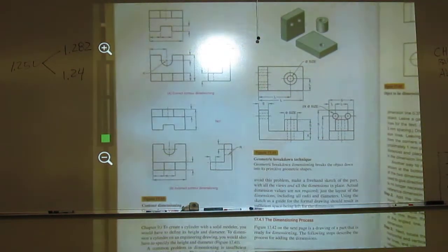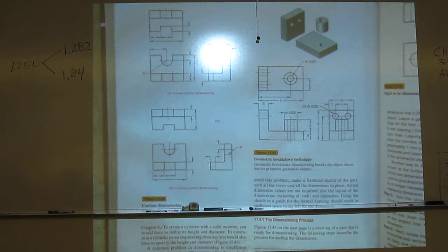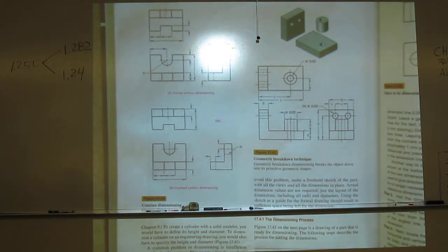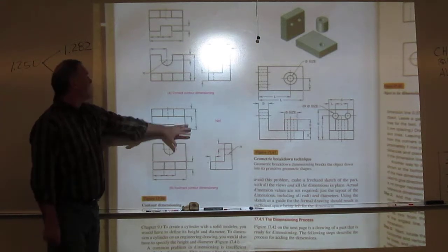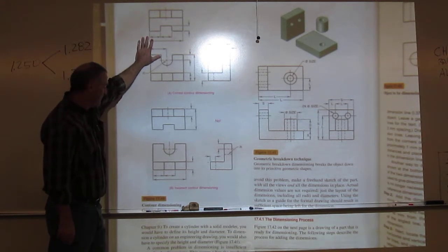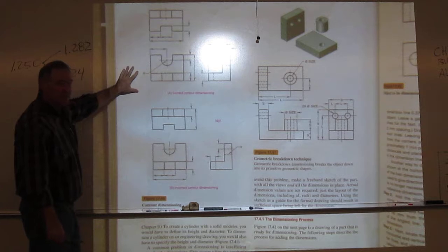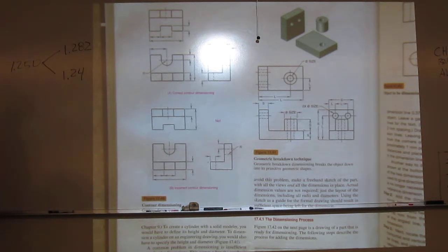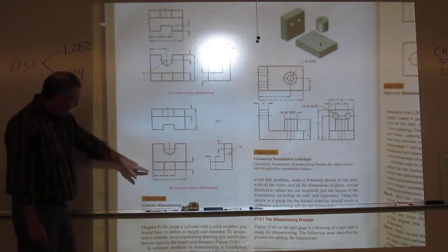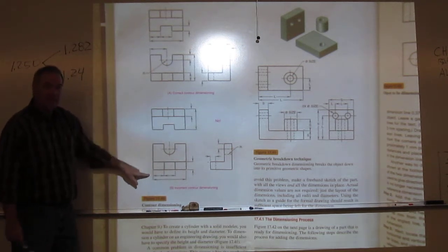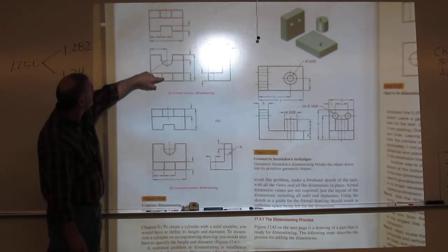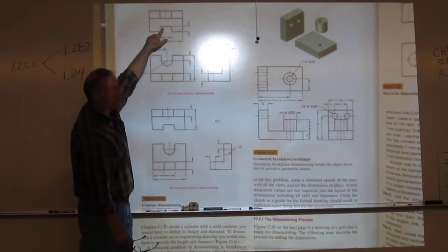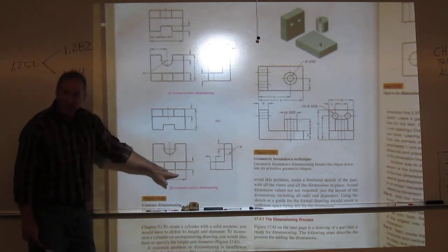Okay, so we'll stick with 1740 for a second because this has contour dimensioning. Here's the wrong way of doing stuff down here. Here's the right way to do things up here. Same multi-views. Now if you look at it, here's how we break out the contour dimensioning. Across the bottom here, they've dimensioned this slot, this little square slot. They put it down here.